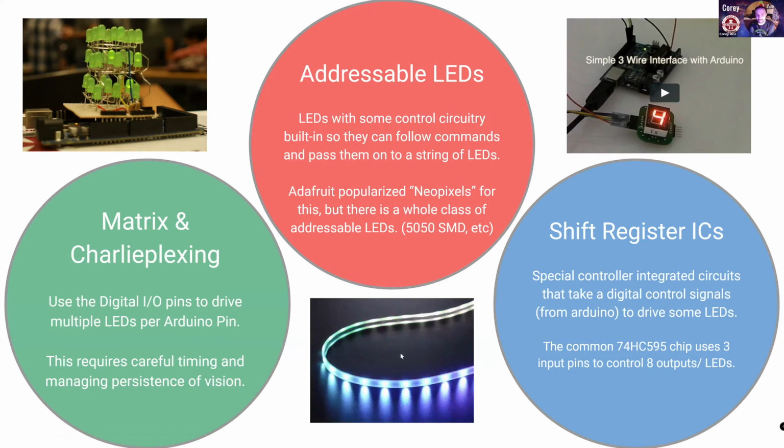These are addressable LEDs, and addressable LEDs has become an entire category. These take digital information and they have a little controller chip inside the LED itself. So you're sending commands chip to chip to chip, LED to LED, and you can write animations that way. Adafruit has really turned this into a solved problem. It's super nice and easy, but you don't even have to use their branded things. They just use 5050 SMD chips. And if you use those, you can design these yourself without buying their product. Their products are great though.